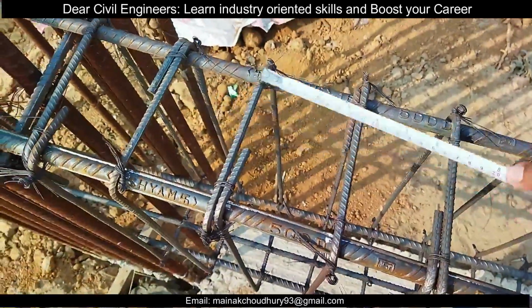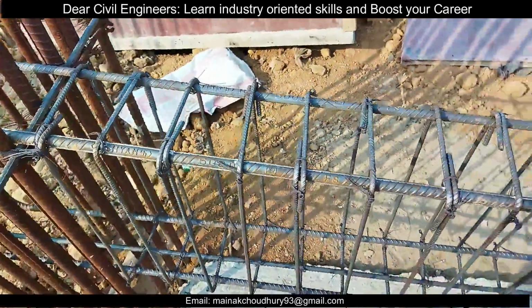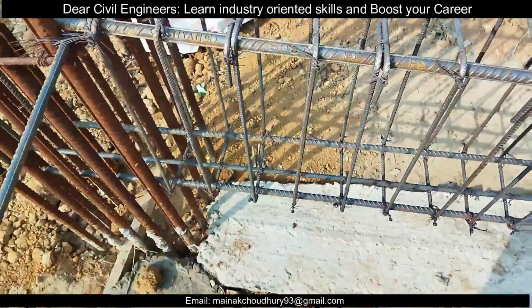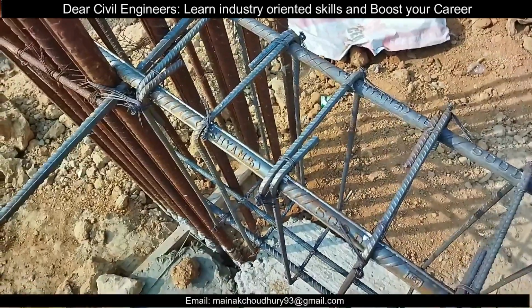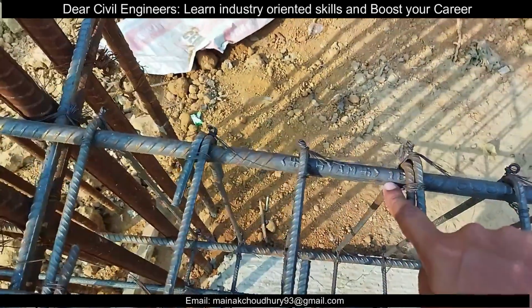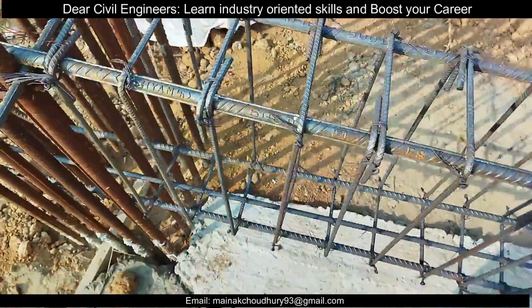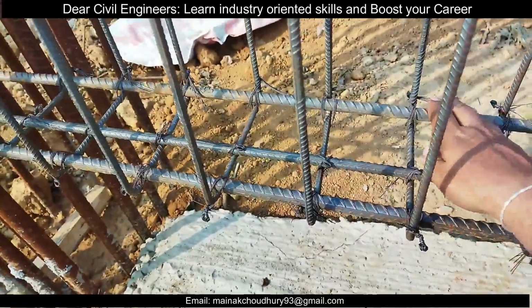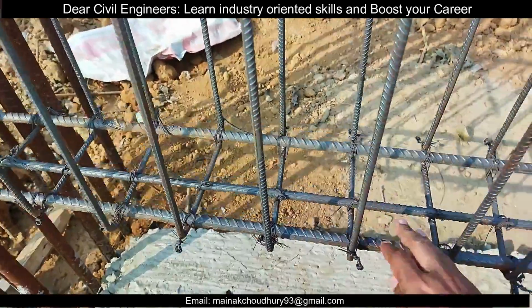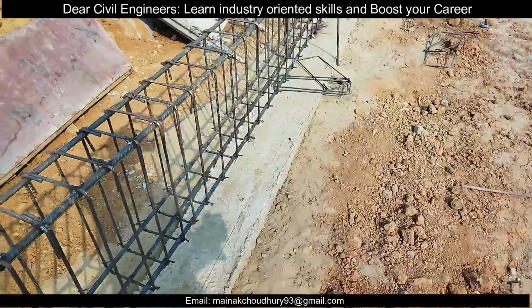So the spacing between the 2 is 100, and since you have taken 2 spacings, it is 200. So this is the next check, and the next check you can do is the main rebar and the extra rebar check. For the main rebar, as you can see here, 16 mm dia bar has been used. 2 bars of 16 mm have been used at the top. At the bottom, as you can see here, we have 2 bars of 16 mm and 1 bar of 12 mm as per the drawing. So it is okay.